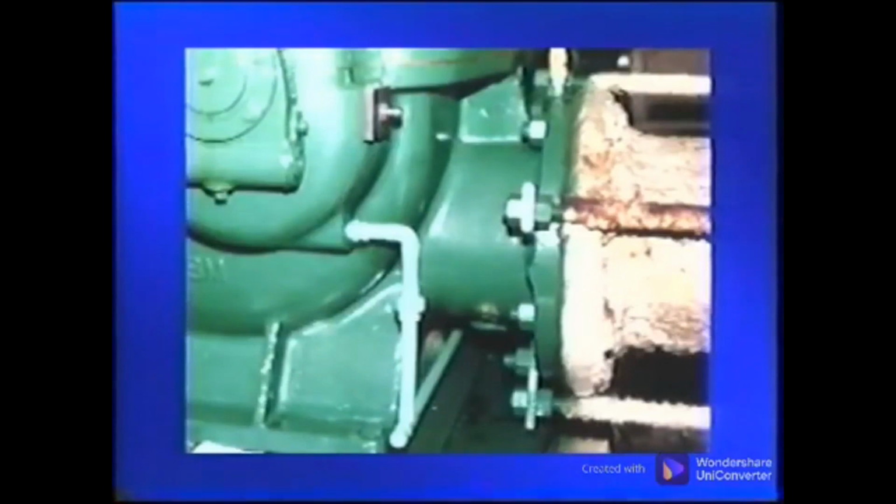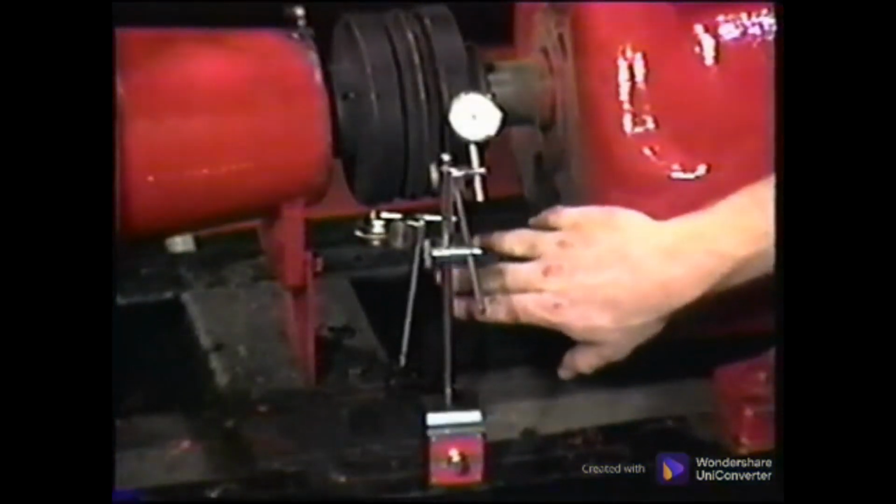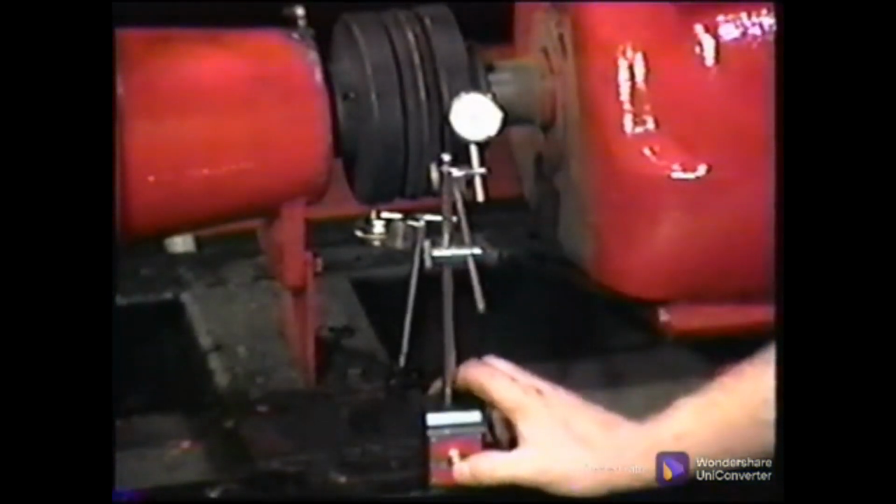Piping strain is any condition when the pipe flanges do not freely make a perfect match, but must be forced into a perfect match by some means. This forced match distorts and weakens both the pipe and the pump. The pump casing is pulled, causing flexing which moves bearing locations, bending the shaft. So a pump motor combination can be in perfect alignment, but connecting ill-fitting piping can force it into a misaligned condition. To check for piping strain, make sure all feet are tightened to the correct torque.